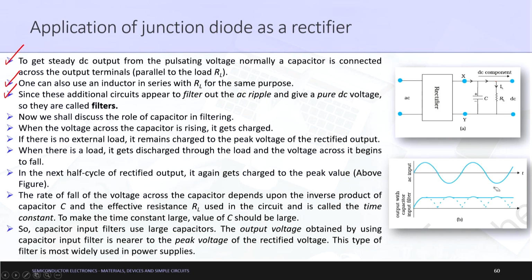As you can see clearly, what is AC? After AC we added a rectifier. What did the rectifier do? The rectifier gives you the voltage like this. Then we added a capacitor with the load, and finally the output which we obtained was this output. What was our main reasoning to do this? We wanted a steady voltage, correct. So, this is how we can get a steady voltage.